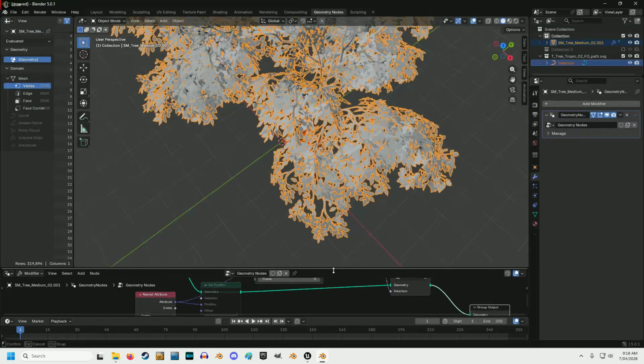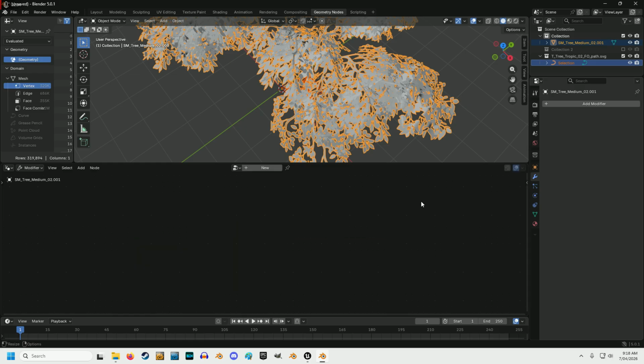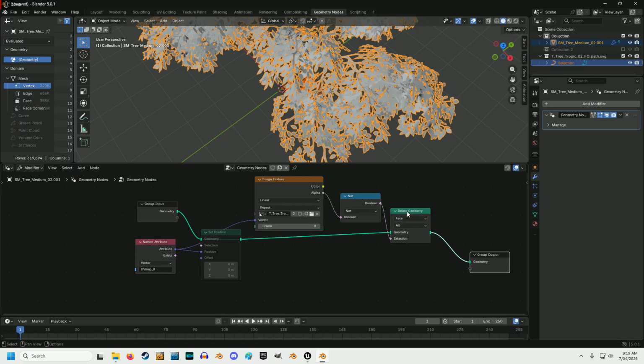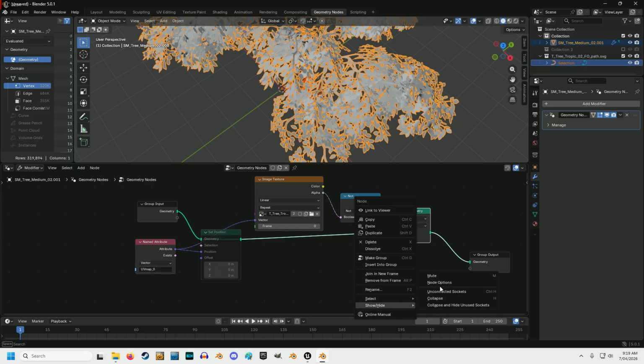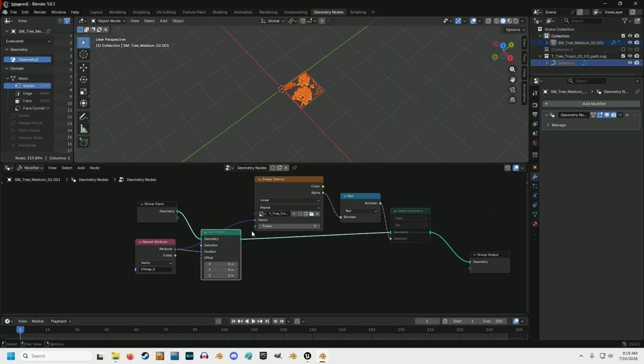So we've done the geometry node thing, so what we can do now is apply that while we're in object mode. Once that applies, this disappears, so we have to go back into add modifier, go to unassigned, and then the highlighted one will bring your geometry nodes back again to be used again, which we're going to do. We'll mute this one, and then unmute this one,